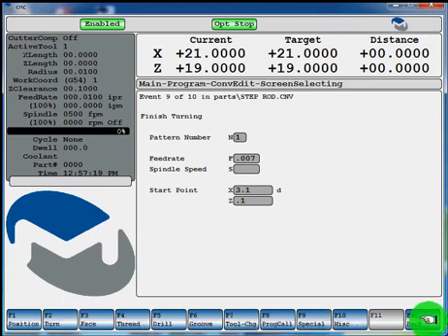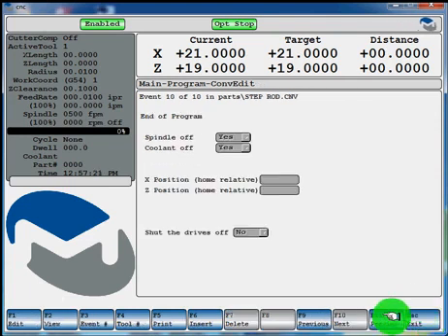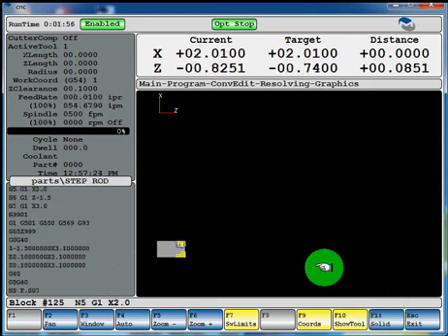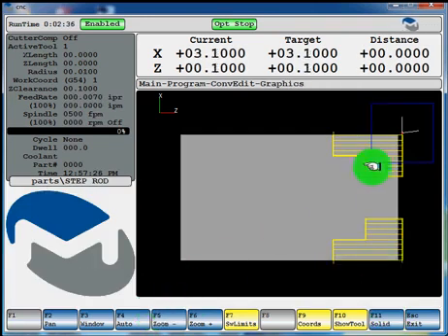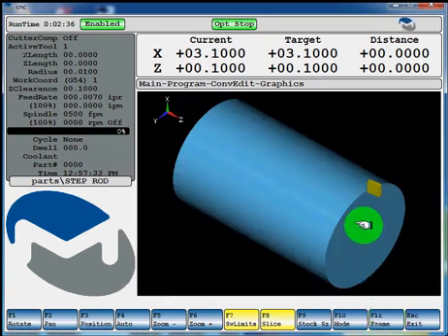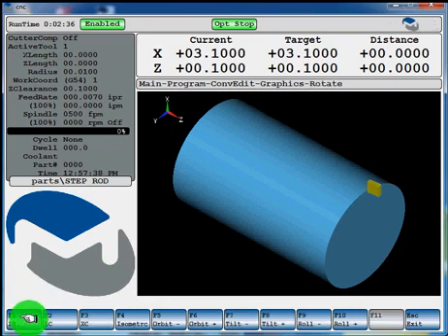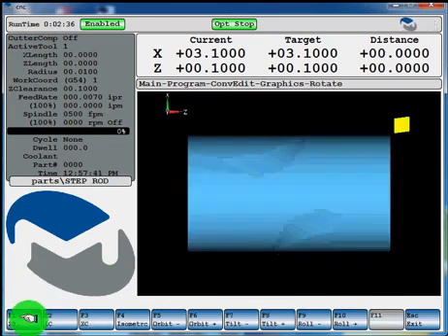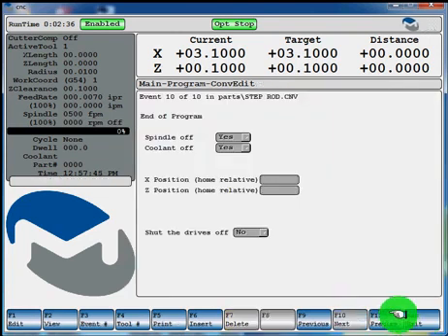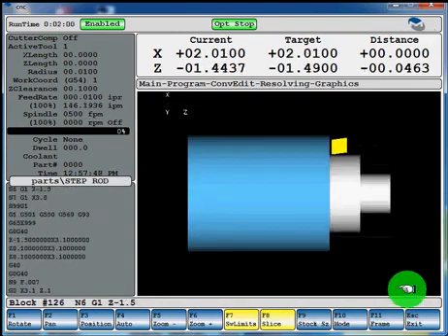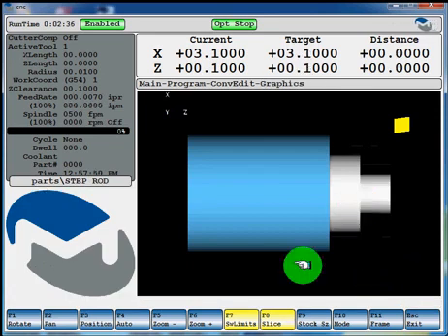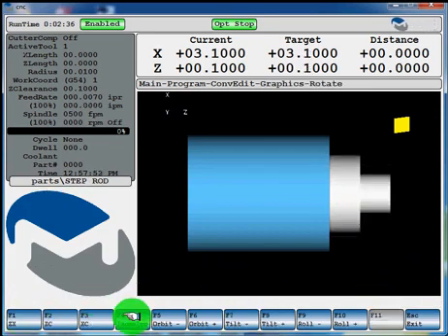Now we're going to hit F11 preview, and that previews all of our lines of geometry. You can see our step rod here. If we hit F11 solid, it'll give our solid model, and we can hit F1 rotate and go to XZ view and escape again, preview it as a solid model, and there's your verified part. Here we rotate as isometric view.